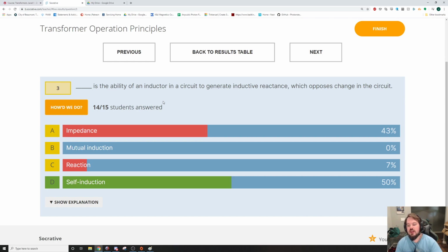So, whenever a conductor induces a voltage on all the conductors around it, it's also inducing a voltage on itself. And that causes it to do less. It's another form of resistance, really. Counter electromotive force is what we call that.